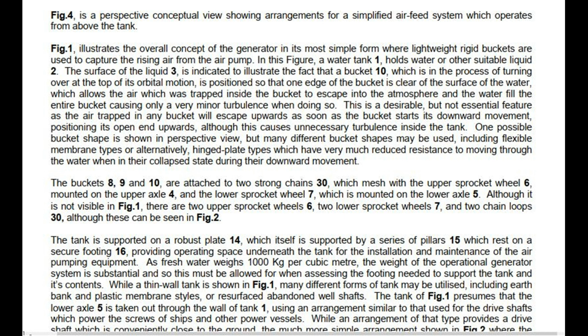This is a desirable, but not essential feature, as the air trapped in any bucket will escape upwards as soon as the bucket starts its downward movement, positioning its open end upwards, although this causes unnecessary turbulence inside the tank. One possible bucket shape is shown in perspective view, but many different bucket shapes may be used, including flexible membrane types or alternatively, hinged plate types which have very much reduced resistance to moving through the water when in their collapsed state during their downward movement.